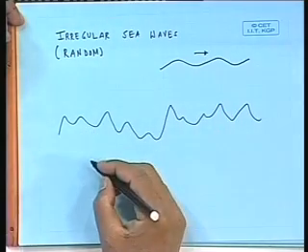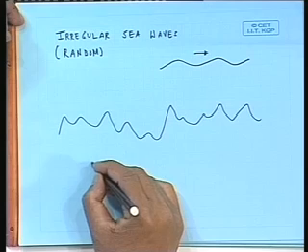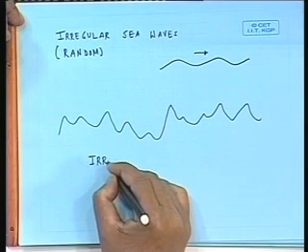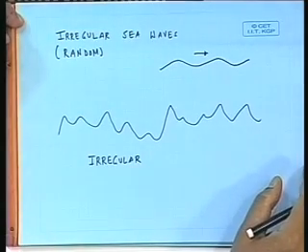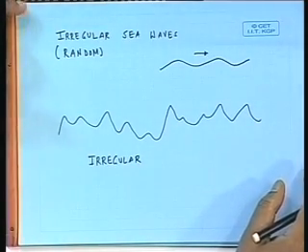This is what we call irregular waves. The word irregular is more used by, or coined by, ship people with a naval architecture background, but eventually when offshore structures started coming up, more civil engineering people were concerned, and they started using the word random waves. Both are the same thing, so we will use them interchangeably. Irregular means random wave. Why are we going to need to study that? Because ultimately our aim is to find out, when I put my ship in a real sea, how the ship behaves.